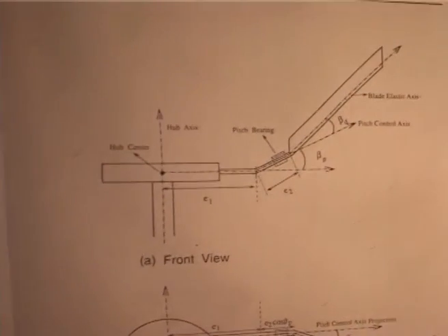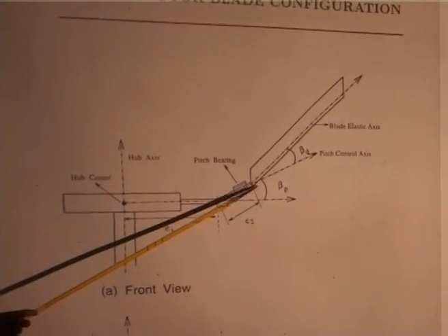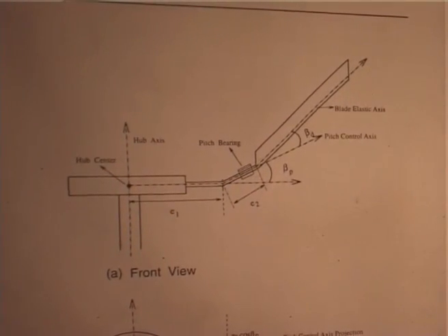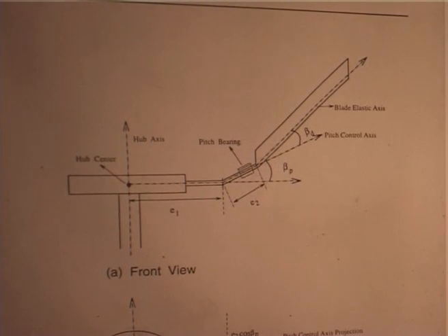These are geometrical, and the order is about 2 degrees. You know the effect of precone is to relieve the root moment, but it has aeroelastic coupling, with tremendous influence in terms of damping. I am not sure whether one blade has both.